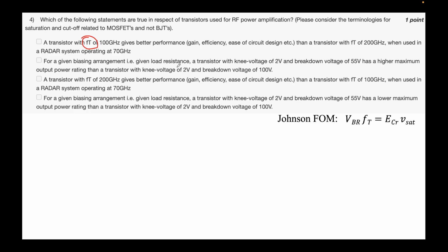to balance the two things, which is the on resistance, right, and the second thing was the breakdown voltage or the leakage current that we had essentially. Okay, here the two things that I want to balance is again the breakdown voltage, which, please remember, depends on the critical field. So critical field is when your bonds will start to break for any given material, right? So breakdown voltage is essentially E critical times your distance that the field is being applied. It's fairly straightforward.